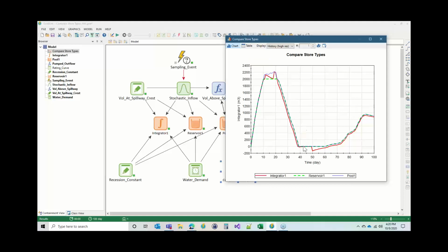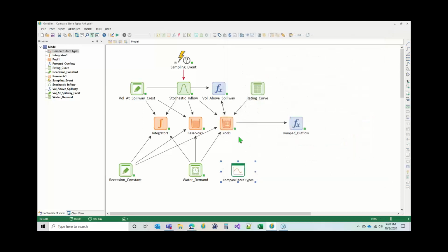We still use that hard lower bound down here, but you could do other things very easily. For example, you could have a status element that Alex will talk a little bit more about. You could do various things to control your water demand. You could turn your water demand off if the water level gets too low or starts to approach the lower bound. So you could essentially avoid all of these inserted time steps as you hit these bounds.